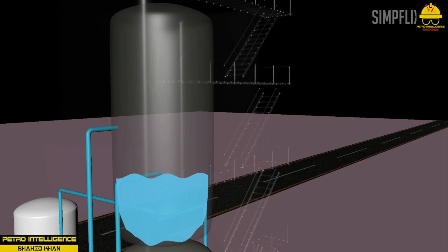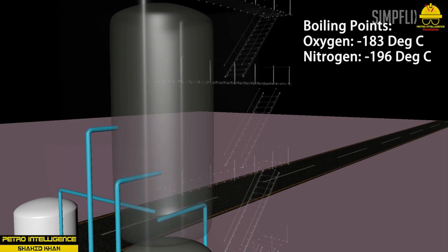In the nitrogen cryogenic process, the warm end process is the same. However, upon entering the cold box, the main heat exchanger rapidly cools the air to -165 degrees Celsius. Nitrogen collects in the top of the column while oxygen pools at the bottom. Liquid nitrogen is sent to and stored in a tank.